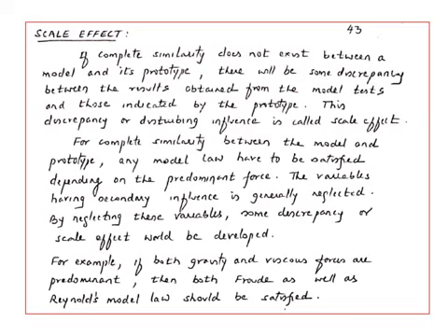If complete similarity does not exist between a model and prototype, there will be some discrepancy. Because now we are trying to satisfy only one of the predominant forces, either gravity or viscous.